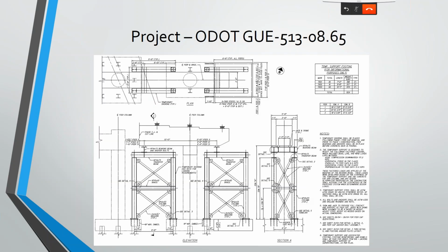Here's what this looks like in plan view. You have basically a leveling pad and base plate coming up into a tower. And then you've got these cross members and bracing, and then it goes up to a header and transfer beams that are taking it. Here are the hydraulic jacks underneath, again, to provide that positive contact with the pier cap. And we have added this extension that's doweled into the existing footing in order to provide a solid unit to support this.